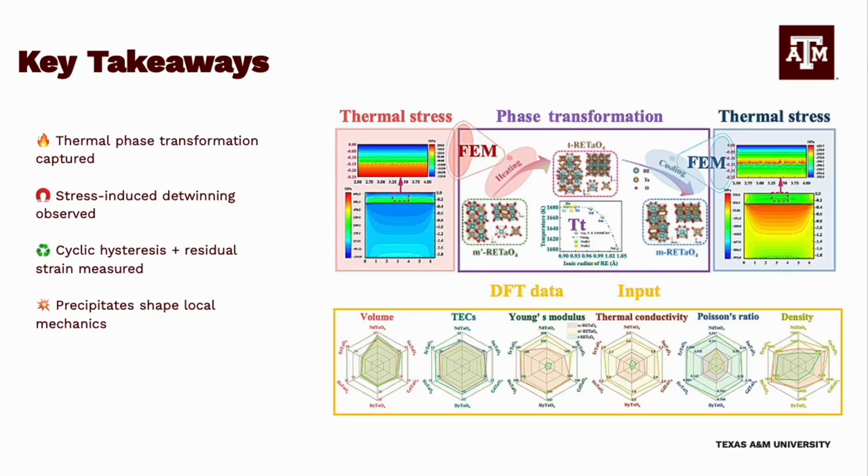My key takeaways. Over the course of this project, I simulated the full transformation behavior of NiTi under thermal and mechanical cycling. I used atomistic simulations to model B2 to B19 transformations. I was able to observe cyclic loading, leading to strain memory and irreversible deformation, which I traced back to dislocation evolution. And I showed that including precipitates adds mechanical resistance, proving that microstructure is essential to performance.